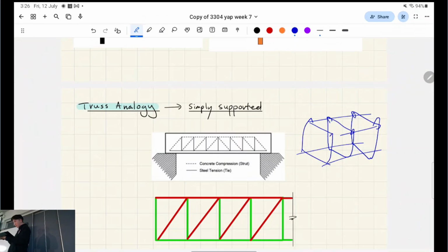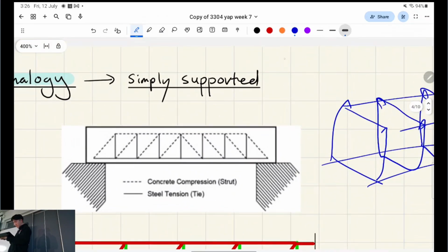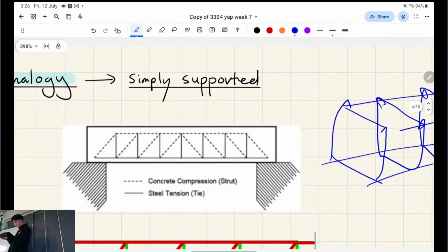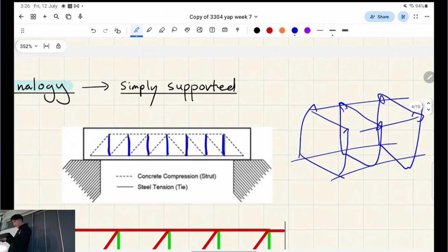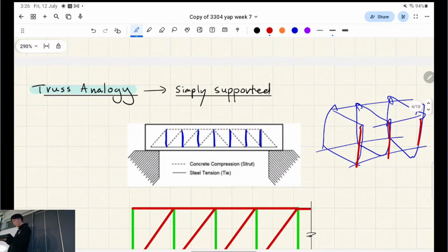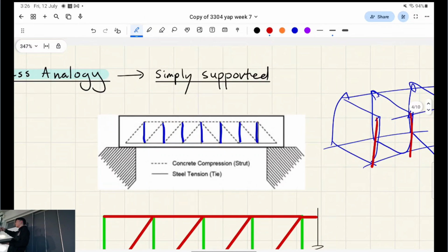Yeah. So basically, the tensile steel, these that I'm drawing here, these are the stirrups, right? We basically have formed a cage where it behaves similarly to a truss, right? So when we're looking at it side on, those vertical steel members, they're taking on tension, right?